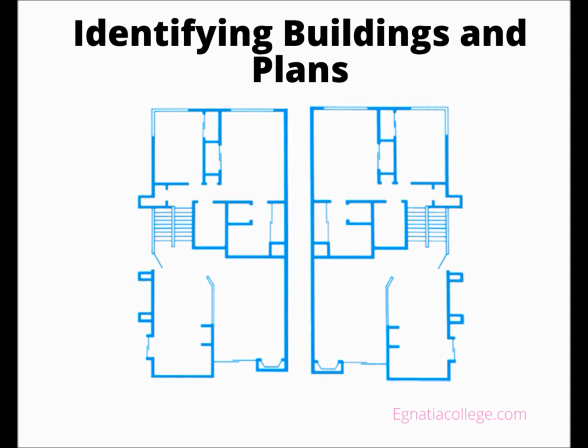One way of reducing the impact of housing on the environment is to increase the housing density in a development. Moving people closer together leaves more space for the unbuilt environment. Many zoning ordinances require housing developments to include a certain percentage of green space. Housing density can be further increased by the use of multifamily buildings. Also, because these dwelling units share walls and have fewer exterior walls, they tend to be more energy efficient.